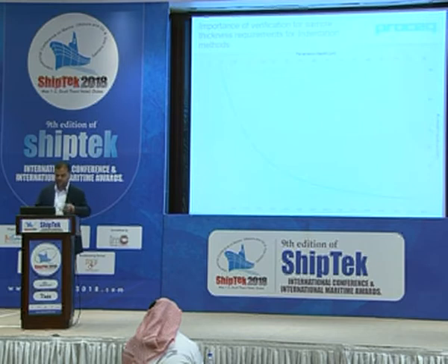Importance of verification, and the sample thickness requirement for indentation methods. If you just have a quick look at this slide, for example, for a 15 micron indentation depth, we need to have 10 times the indentation depth. So we are talking about 15 times 10, which is 150 microns. So the minimum sample thickness to measure with the portable Rockwell instrument is almost 150 microns in this case.